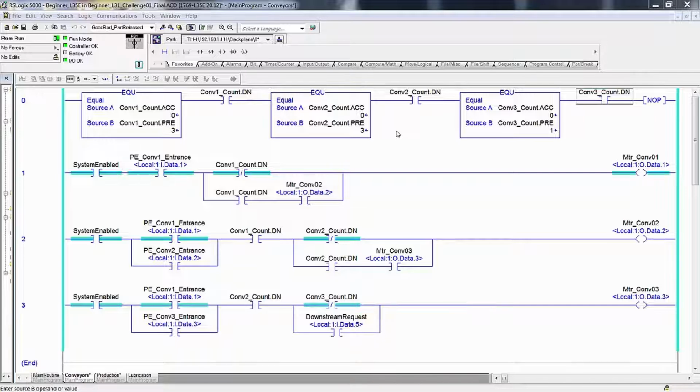But let's do photo I, entrance 1. See, there's nothing in the accumulate. I let go. Now you see over here there's 1. Hold it down till it times out. 2. Hold it down till it times out the debounce. 3. Now you see the done bit comes on.